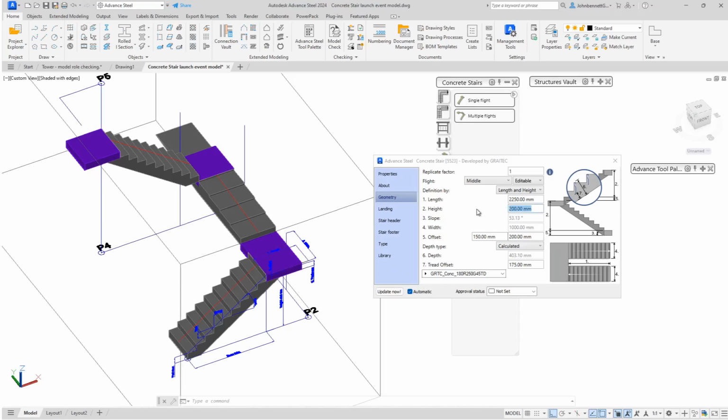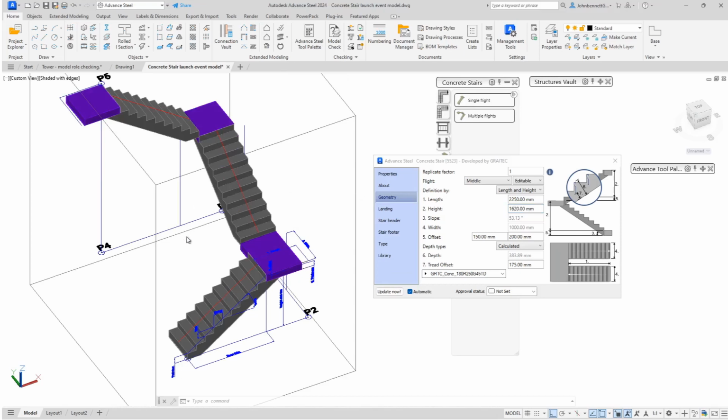And don't worry, because it probably looks a bit strange when you first do this. And there we go. So we've got the basis of what we need now, and let's just set that in there. So that's setting the height of that first nosing again. Now at the moment we can see it's turned the landings here. You've got 2 quarter landings, and we've got a top landing. A field that has become active here is the horizontal offset at the top of the first quarter landing.